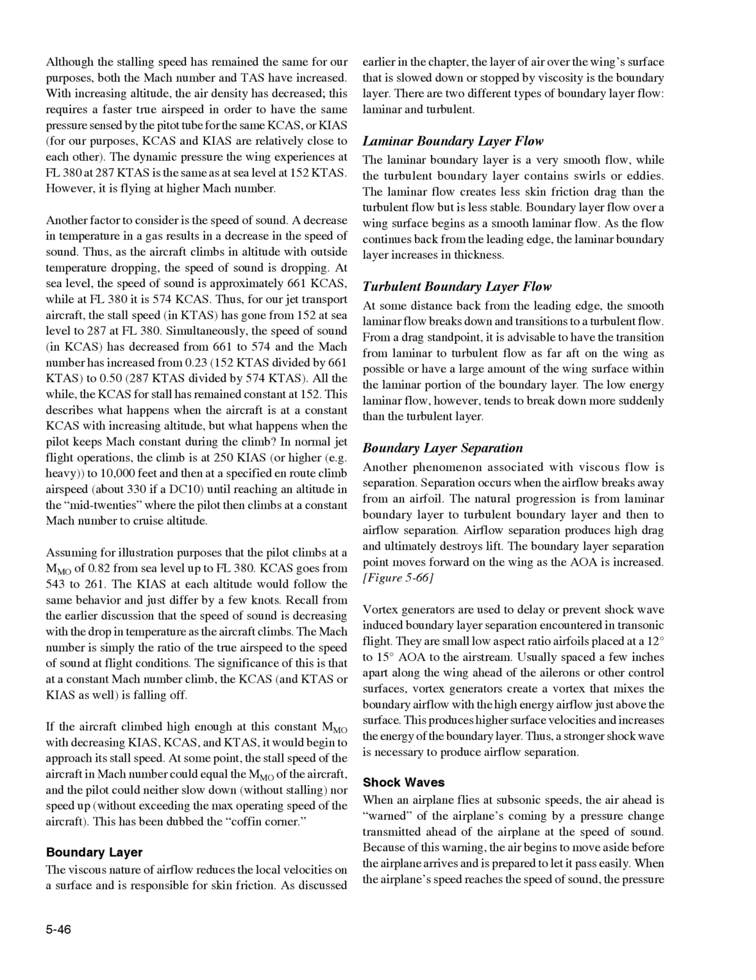Simultaneously, the speed of sound, in knots, has decreased from 661 to 574 and the Mach number has increased from 0.23, 152 KTAS divided by 661 knots, to 0.50, 287 KTAS divided by 574 knots. All the while, the KCAS for stall has remained constant at 152.